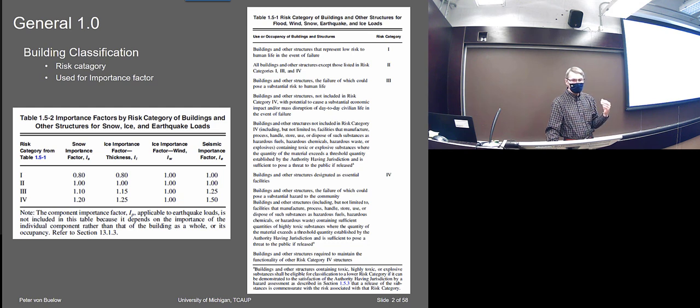So they give you a bigger safety factor on buildings that are more important, and they cut the margin a little closer on buildings that aren't so important. You could make buildings stronger and stronger, right, and be certain they would never fall down under any load, but it would be unreasonable. You would be wasting material, and it just wouldn't make sense.